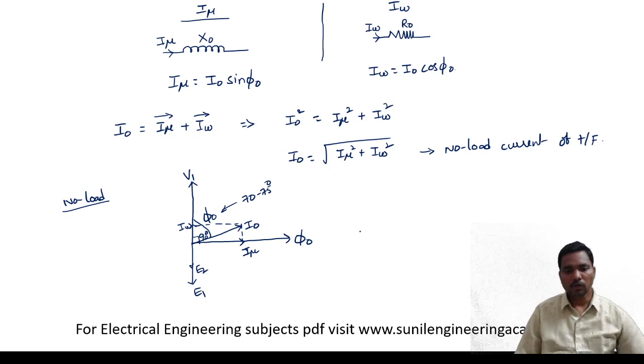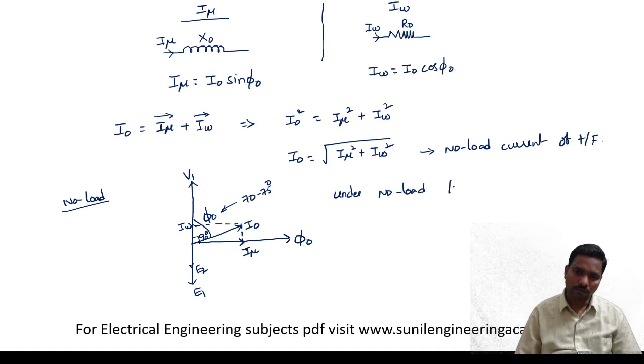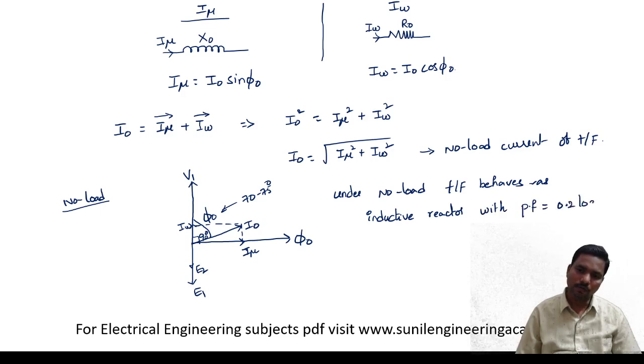So from this we can say that under no load, the transformer behaves as an inductive reactor with power factor approximately 0.2 lag.